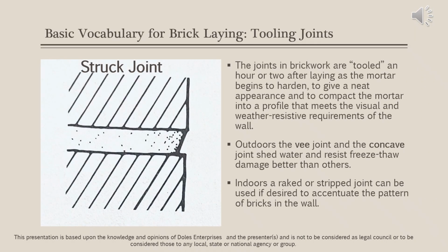Proper tooling of the mortar joints for brick does not only provide an aesthetic look, but also has weather-resistant values. The joints in brickwork are tooled an hour or two after laying as the mortar begins to harden, to give a neat appearance and to compact the mortar into a profile that meets both the visual and the weather-resistive requirements for the wall.